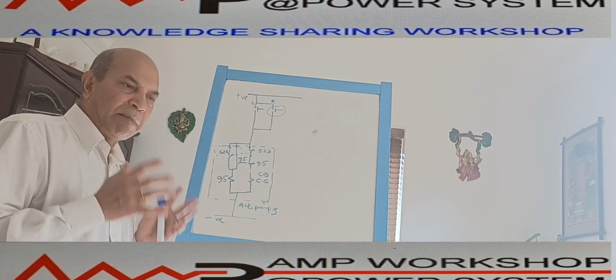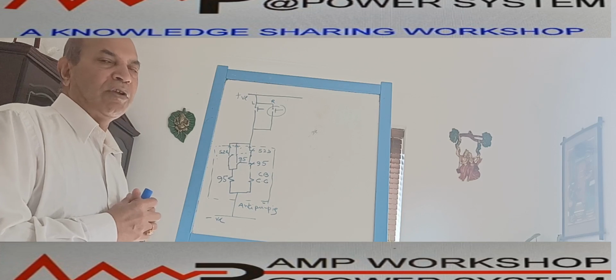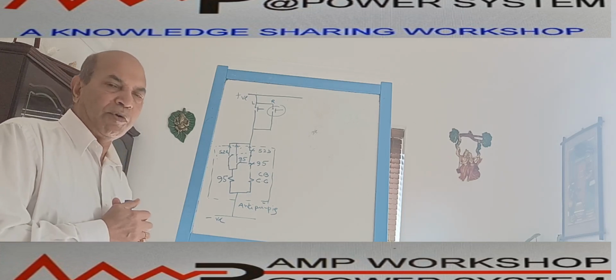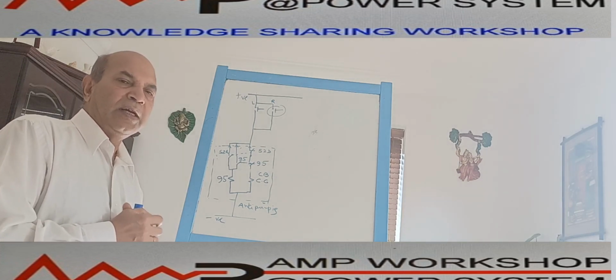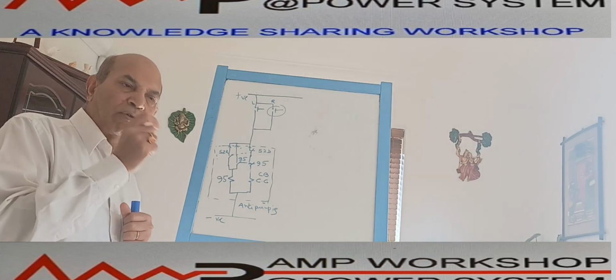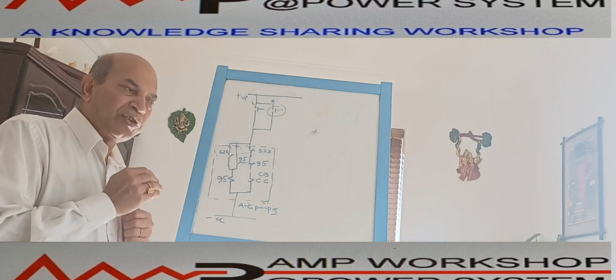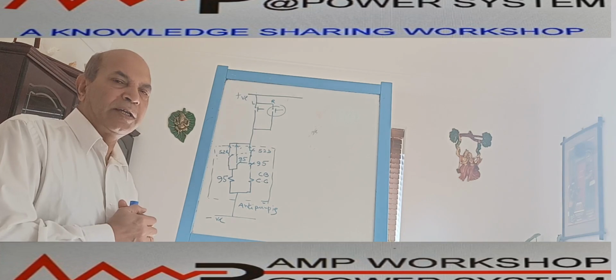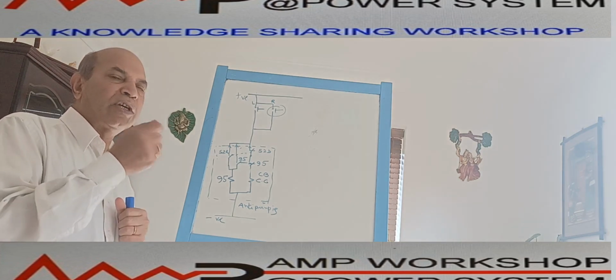This anti-pumping device is doing one important thing that our friends addressed: it is not allowing a continuous closing command to be maintained. That is one part. The second part is also preventing problems sometimes when we do synchronization.